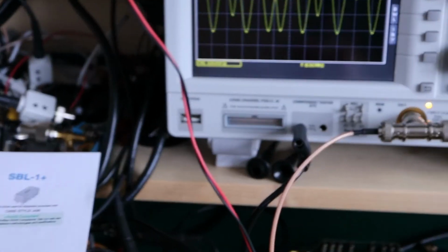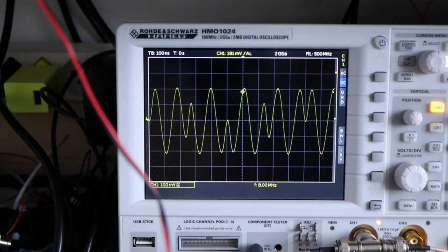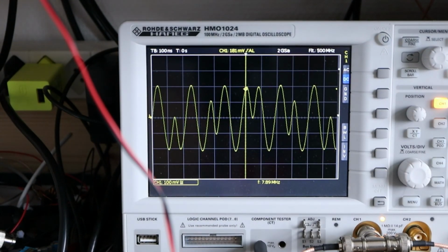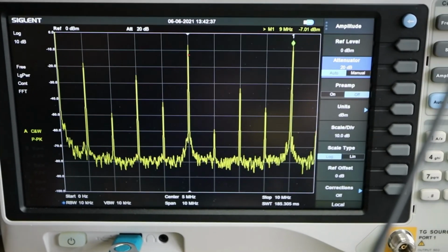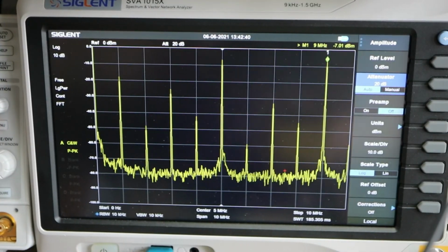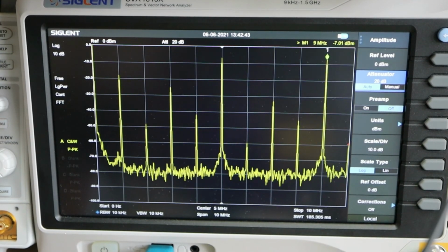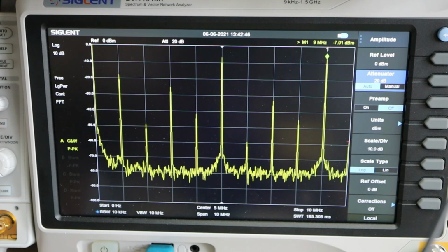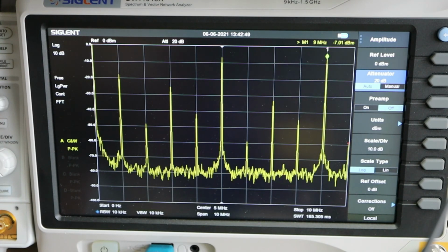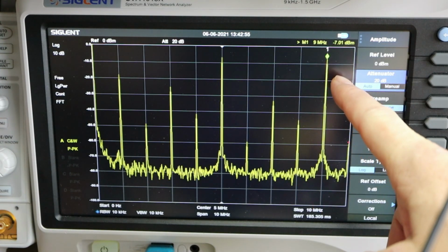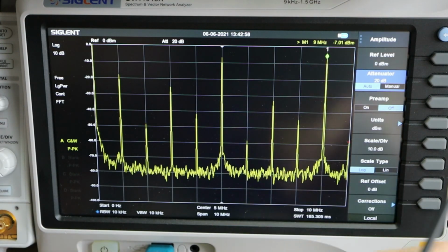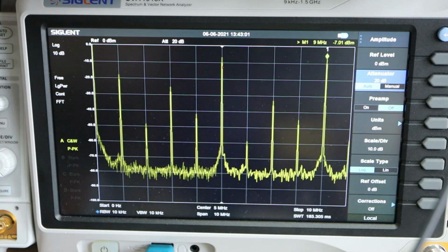If you take a look at the voltage on the scope, it looks really nice, as it should be, and it's performing really well. However, we have almost 100 milliamp current drawing, and so this is certainly not a low power device at all. I have 3 of those mixers at 300 milliamps right away for the radio, without any other electronics. So that's a lot. And on the spectrum, you see again the 9 megahertz spectrum and the 5 megahertz spectrum as expected, and a few harmonics, relatively a lot.